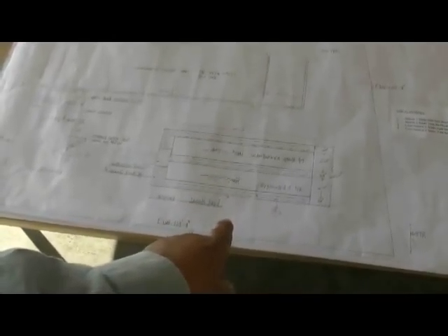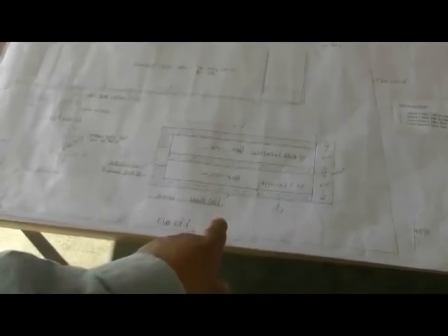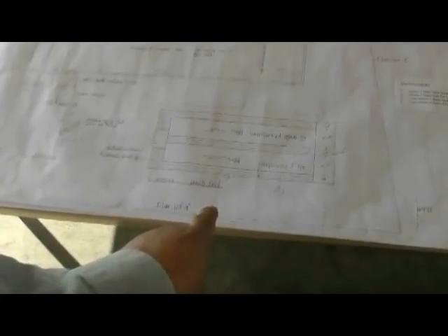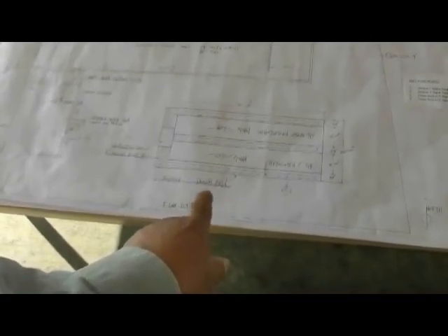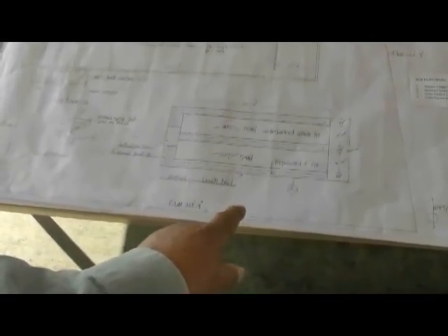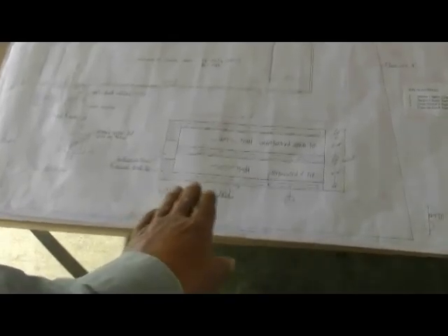And I want to make a very, very important note here. When this leach field is established, and you probably know this, we do not want to use it for planting anything, to stage anything, to park cars over, to pour concrete over. It's forever and ever a leach field, and it should be established as that for the course of the life of the church. Okay?